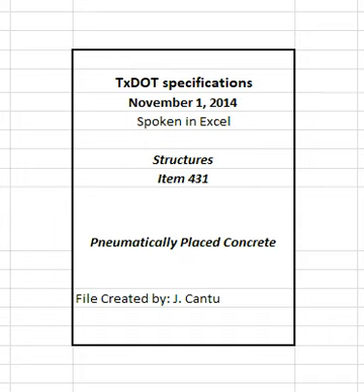Apply the concrete using pneumatic equipment that sprays the mix onto the prepared surface at a velocity less than 100 feet per second for construction of portions of structures, repairing concrete structures, or encasement of structural steel members. Minimize rebound and produce a compacted dense homogeneous mass. Do not apply concrete if high winds will prevent proper application or if rain could wash out the concrete.